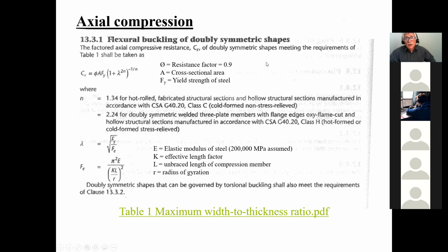Okay, in steel, as a matter of fact, this is where you're going to appreciate. You're going to look at the Rx value, you're going to look at the Ry value. In other words, the radius of gyration about the x-axis is always going to be bigger than the radius of gyration about the y-axis. And then when you do your slenderness ratio, that's the one that's going to govern. You always have a strong axis and a weak axis.